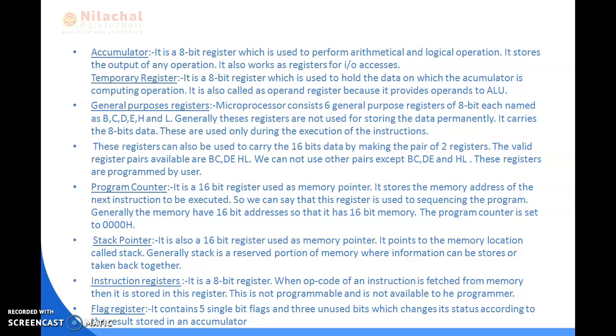At least one of the operands has to be in accumulator A. Thus, to add B and E register and to store the result in B register, the following has to be done. That means it is possible to use these registers as pairs. So, BC, DE and HL are used for 16-bit operations.